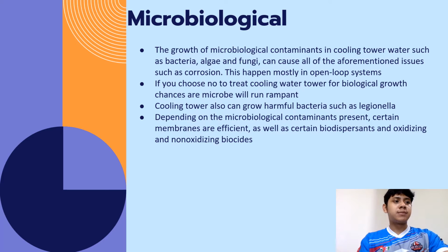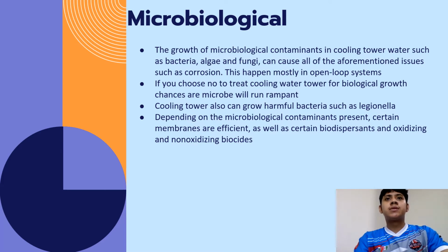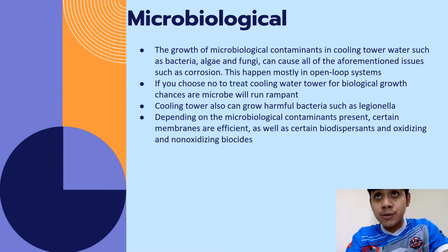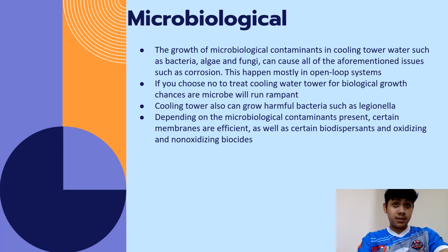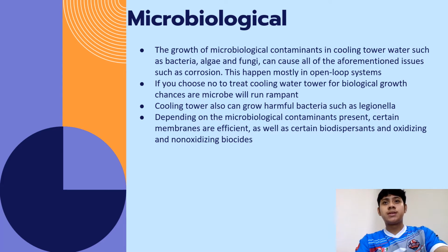Microbiological. The growth of microbiological contaminants in cooling tower water such as bacteria, algae, and fungi can cause all the aforementioned issues such as corrosion. This happens mostly in open loop system. If you choose not to treat cooling tower water for biological growth, chances are microbes will run rampant.